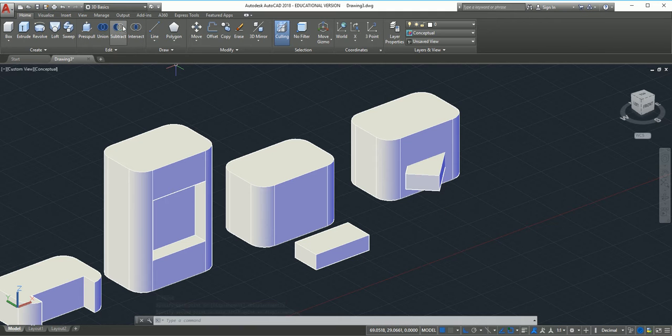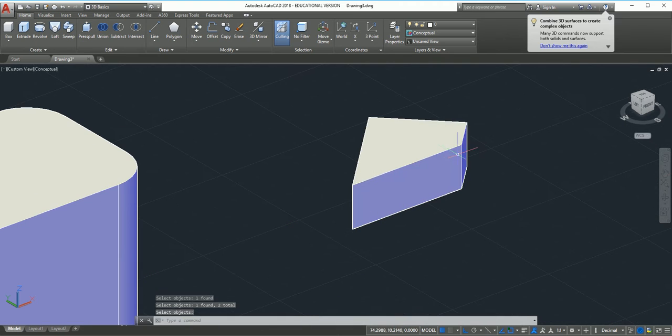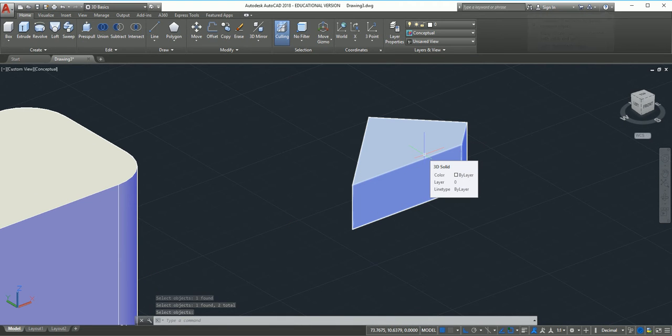So the last one of the editing tools is intersect. If I pick both of my objects and I right click, it's only going to give me the shape left that is common between all the shapes. I don't think I've ever tried it past 4, but in theory, you should be able to intersect 12 objects at once, as long as they're all intersecting. If they're just touching face to face, I don't think it counts. But as long as they're overlapped on each other. Cool?